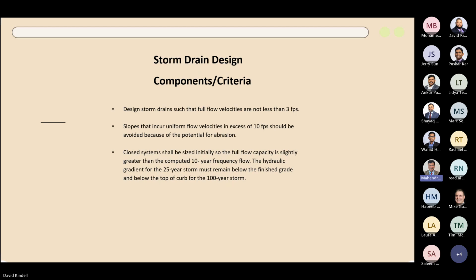That camera is 360-degree rotatable, can find if there is any structure damage underground, they can locate it and give you a linear footage wise video, so that you can know where the damage is, starting from 0 to which station. So yeah, that site is correct. That is available, not a big effort. But it depends, Puskar's question is, it depends on whether it's covered in our scope or not, but it is doable. So basically, we need to give them linear footage or number of pipes.